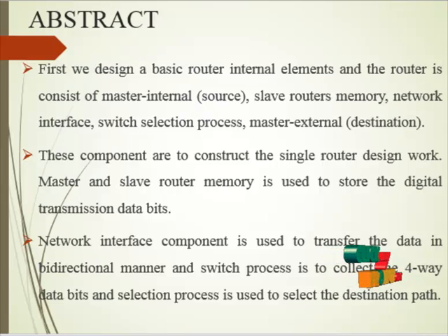The routing computation unit, the virtual channel allocation unit, and the switch allocation unit are responsible for the control signal generation within the router pipeline during the travel of the packet. The 5x5 crossbar connects the input ports of the router to the 5 output ports, facilitating packet travel.